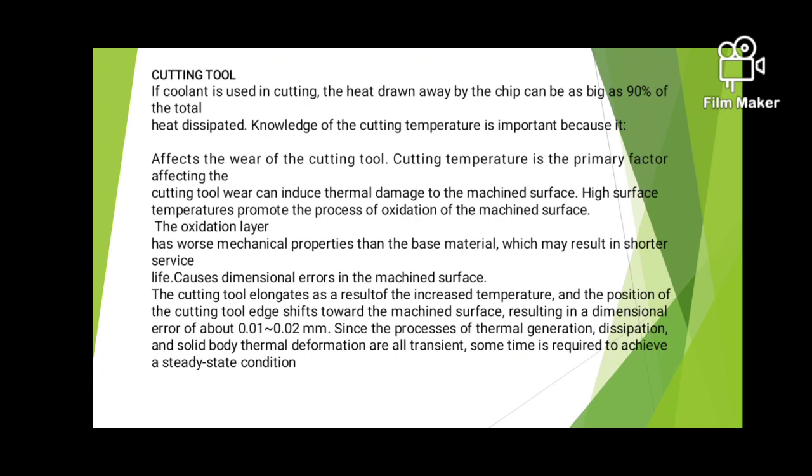Wear can include thermal damage to the machined surface. High surface temperature promotes the process of oxidation of the machined surface. The oxidation layer has worse mechanical properties than the base material, which may result in a shorter service life. It also causes dimensional error in the machined surface.